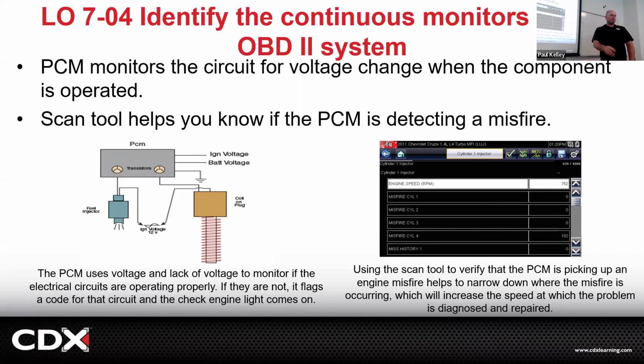But my point to you is the way the onboard diagnostic system works, it doesn't actually know that it's the injector. It could be the injector. It could be an open coil inside the injector, but it could be an open in this wire here and this wire here. It could be a bad connection here. It could even, in some rare cases, be in the circuit inside the ECM. So when you get that code, the possibilities most of the time are going to be the ECM or the PCM itself, because it's got a little printed circuit board, the little green board with the little circuits drawn on there. It could be that.